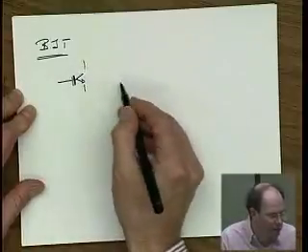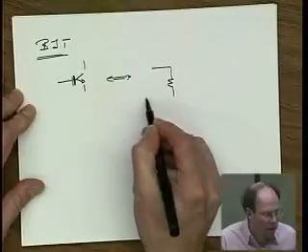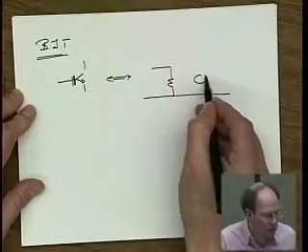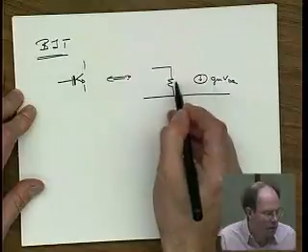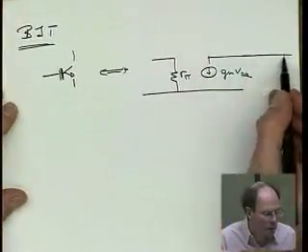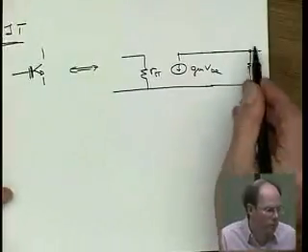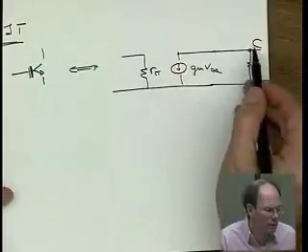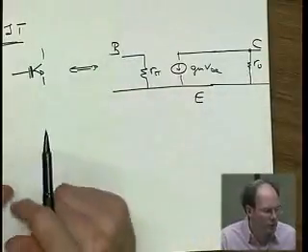So a bipolar transistor, I'm used to MOSFETs. A bipolar transistor has, of course, also a small signal model. I'm drawing only the low frequency small signal model. gm VBE, or r pi, and then, of course, also an r out. That's the collector. Emitter. And the base. And that's VBE.